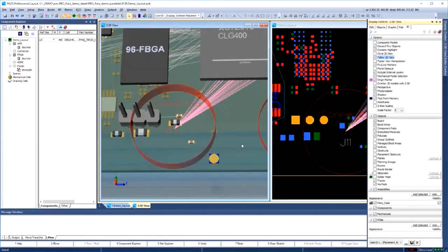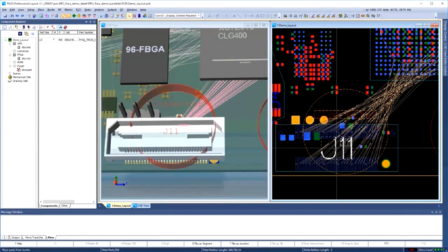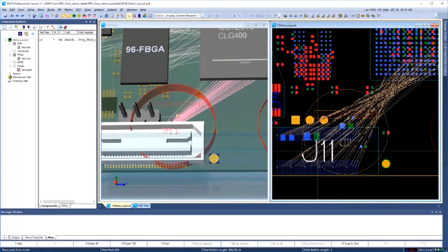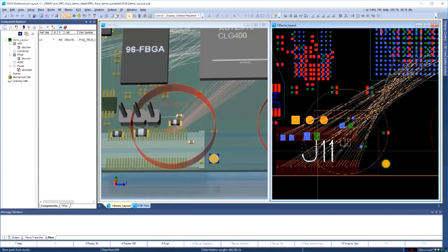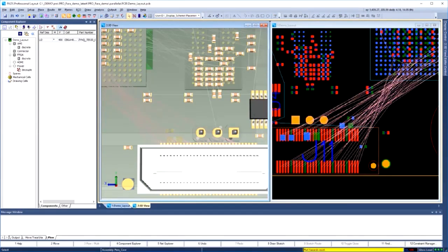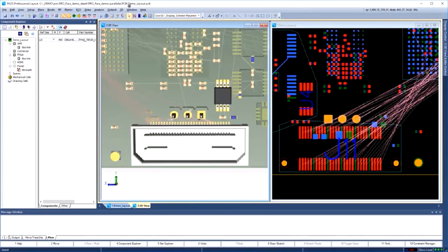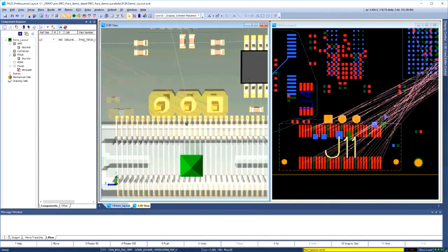While placing, view both the 2D and 3D representations of the part concurrently, and either drive or follow the 2D view while using 3D. Connector placement is especially helpful to view in 3D to make sure you get the orientation correct the first time. PADS Professional utilizes photorealistic solid models that can be used to verify component clearances when placing. The cell manufacturing drawing may not include all the finesse of the full 3D model, and it can be difficult to quickly visualize the orientation of a component.